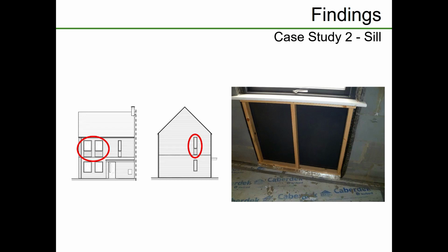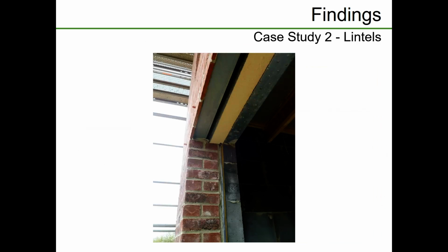Yes, they did infill between the studs with insulation, but that posed a bit of a problem actually in terms of assessment, because the conventions for thermal modelling deal with normal jams where you've got a wall and then the window. What it doesn't deal with is a scenario where you've got this infill panel behind the window. So I had to devise a procedure for calculating the thermal bridging at that point. So what I'm pointing out here is that some of the conventions that we use for energy assessment, whether it be the thermal modelling or whether it be whole building modelling, have gaps in their procedures. So they need development, okay. So we're coming at this from all angles really.